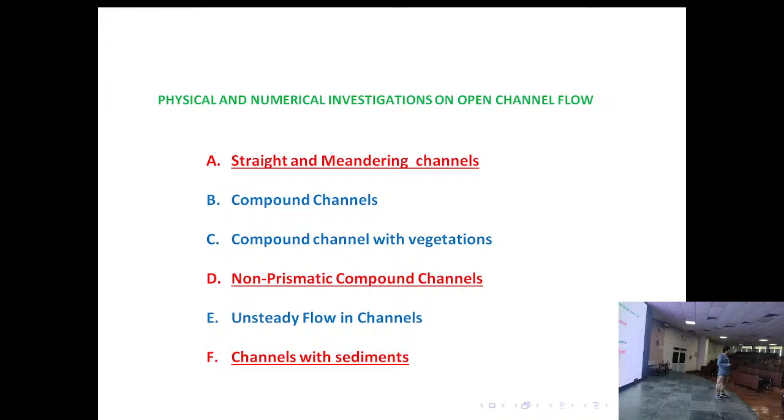Then compound channels, rivers with flood plains. That is a uniqueness because of momentum transfer. Again, there is a loss of energy that you cannot see or visualize in the simple Manning's formula or Chezy-Darcy's. That also we have already contributed to.